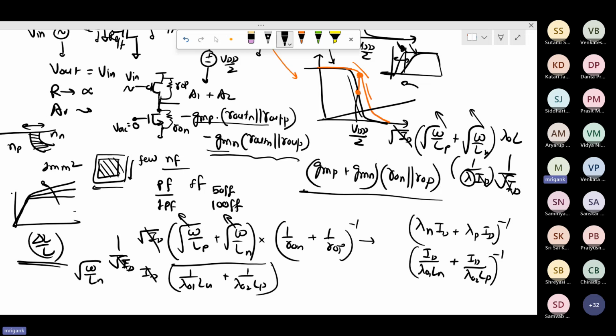Yes. So the bandwidth of the circuit depends upon the RO, right? The RO is larger. Your RO is larger, that means you are going to get lower bandwidth. The speed of the circuit will become slower and slower. So this also should be clear.